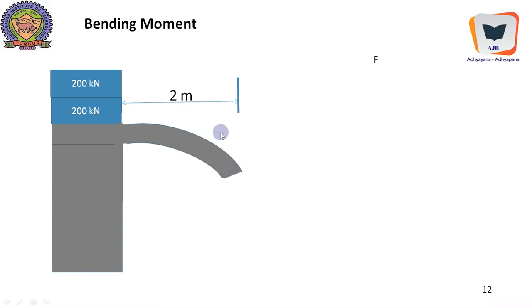So this is really the bending action. So the bending moment, which is load into this perpendicular distance, will really make the beam bend. And it acts exactly over here. And we can calculate the value of bending moment at different sections. As we go from here it is 0 because there is no moment arm. As we move inch by inch over this beam, we will culminate in the total bending moment, which will be very critical at the support. Therefore, bending moments will bend the beam.